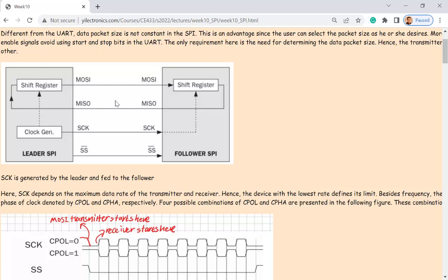Come on, definitely. Arduino has SPI. Let's just connect. If you open up the pinout of the Arduino chip, you can see MISO, MOSI, CK, CS, right? Sometimes SS, CS. It's just chip selection. So just hook these four pins to the sensor and use whatever SPI package you can find online. It's just a function, and you can define the speed of the SPI and the data length of the SPI.